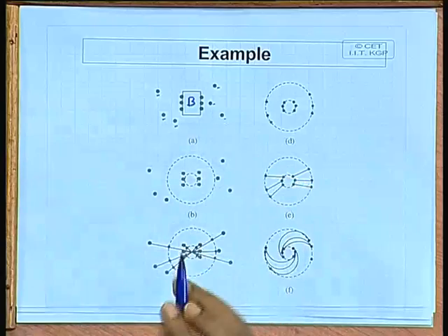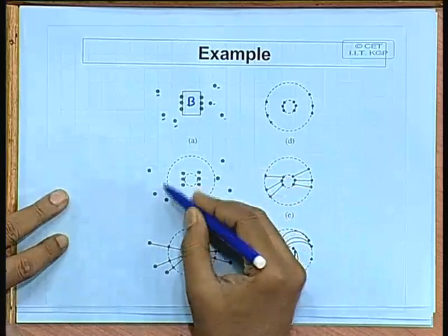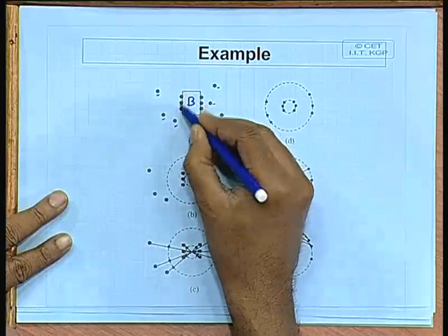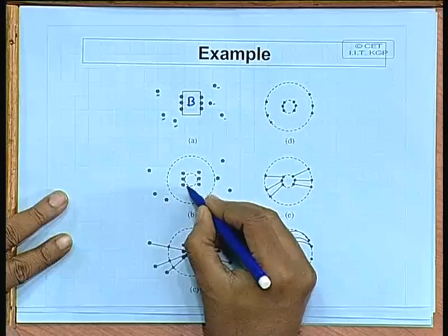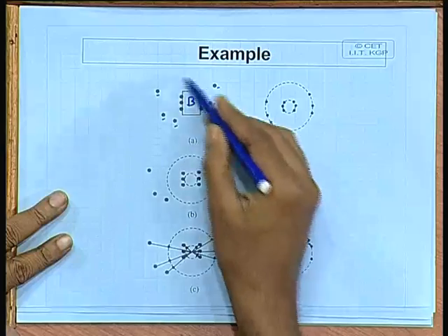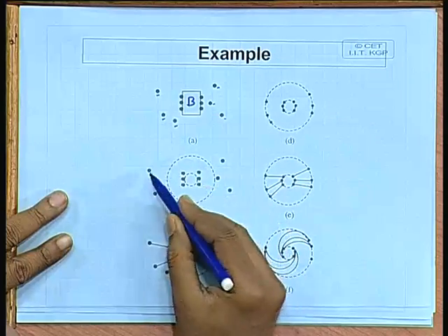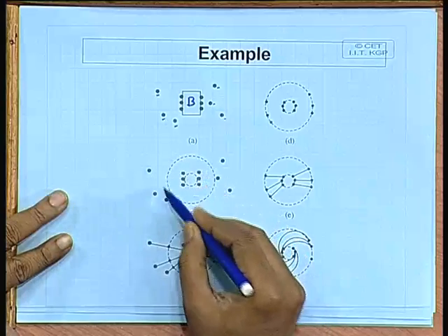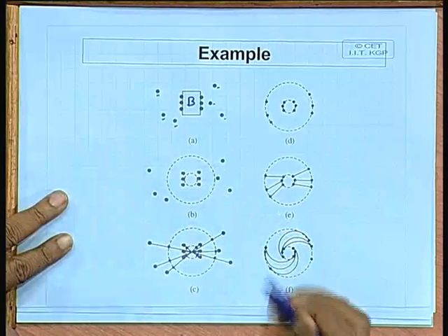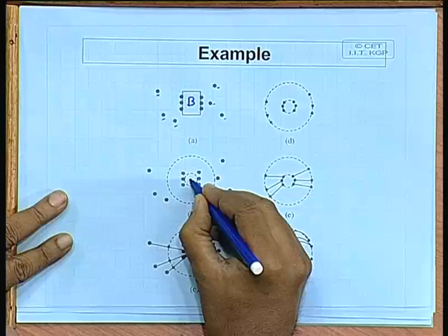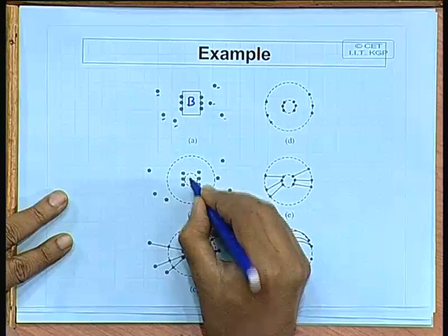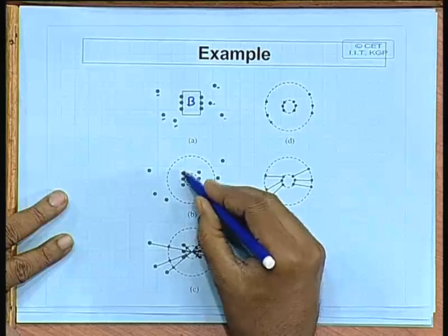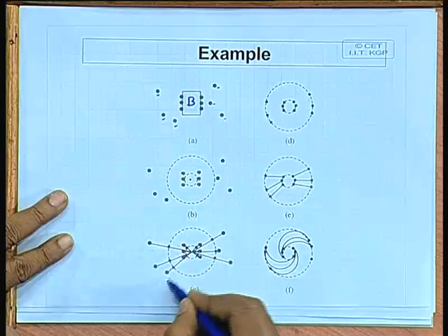Okay. First thing is that you define 2 imaginary circles. The first circle will be just inside the inner pins like this. The second circle will be just inside the outside points. This was the nearest point, so you define a circle like this. The third step is you take the center of the circle and draw straight lines to all the points of the inner and the outer circles.